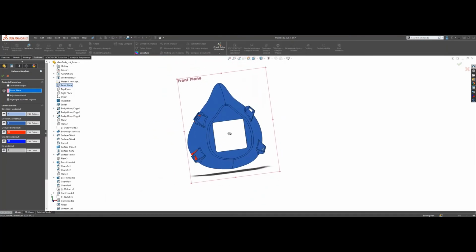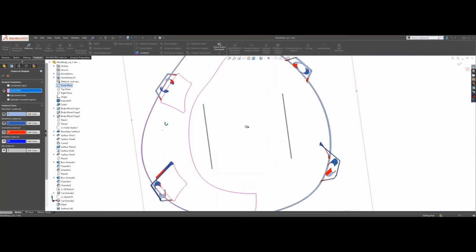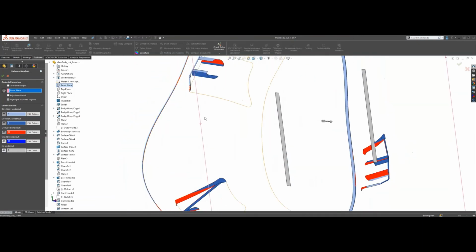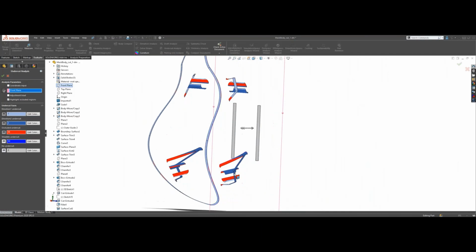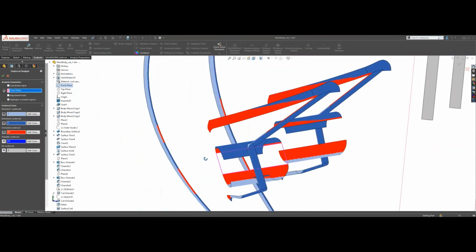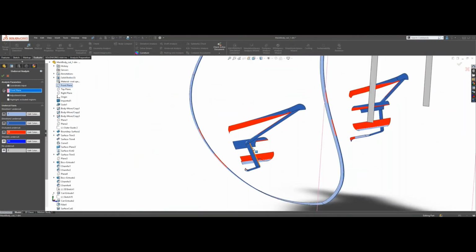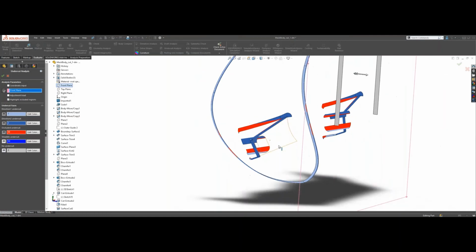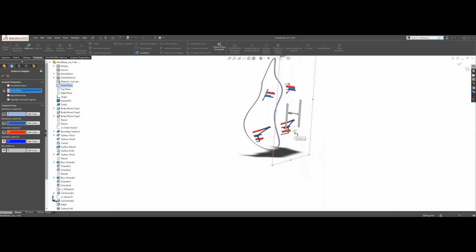it just takes a little bit more to investigate, because a lot of times it can just be a fillet, or perhaps an area. I'm actually going to show you here, so you can show them and hide them. But you can see here for the strato undercut, there's some fillets showing, and some different faces that are considered strato undercut faces. So those are areas that you are perhaps going to have to do a little bit more research on, perhaps contact your manufacturing company that makes the molds, and see how they are going to try to make those areas for that mold.